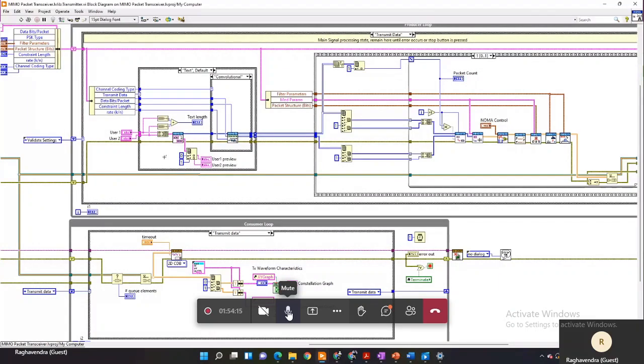Yes, so at that time, that probably won't affect the way that you do whatever RF signal processing you do, but you will have to send the information to your receiver. So let's say you write your audio file at 44 kilohertz. Oh yeah, actually this data you will have to give to your USRP. You're right. This 44 kilohertz information, the sample period information, you will have to give to your USRP. So in that case, it will be relevant.